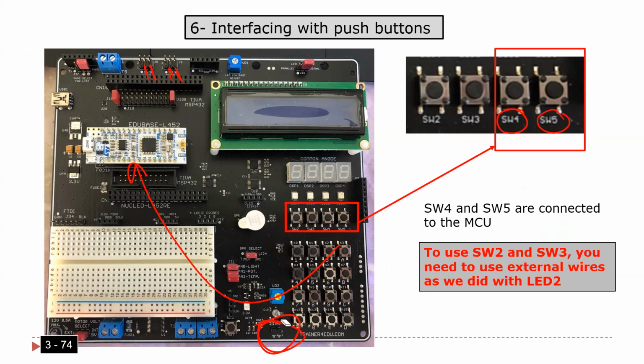Okay, so what you can do, you can connect the ground, for example, to here. Where is 5 volt? I'm not sure if there is one closer than this one. I think this is the closest one. So you can connect 5 volt from here to here. Okay, sorry. If you do that, you make a short circuit. Connect it to here. And then you can connect the switch this way, with both resistors.